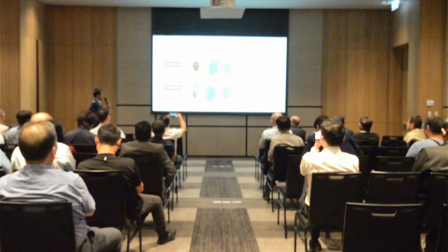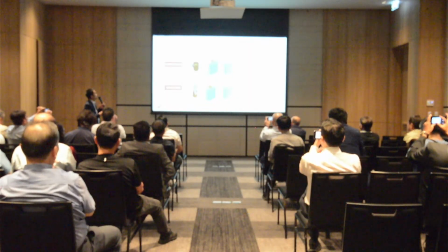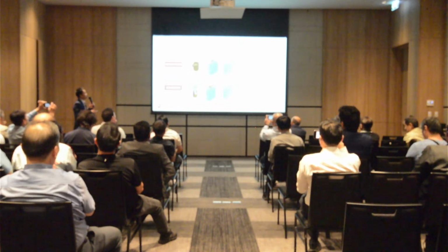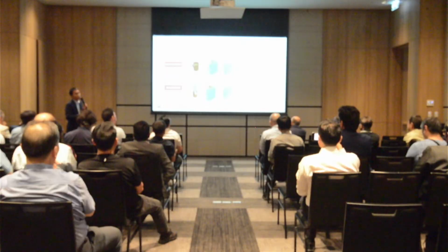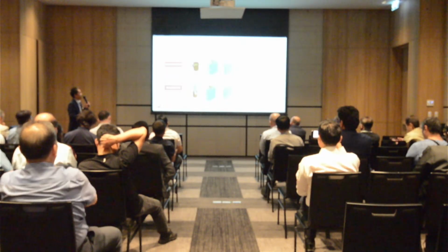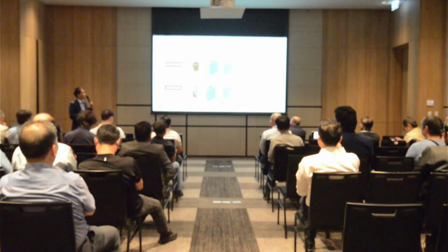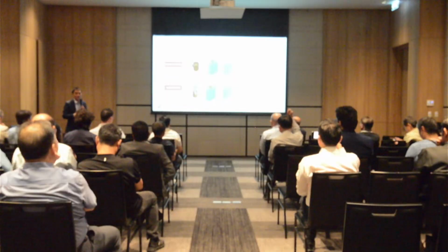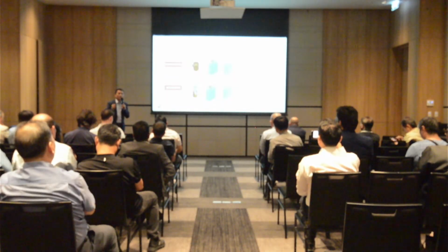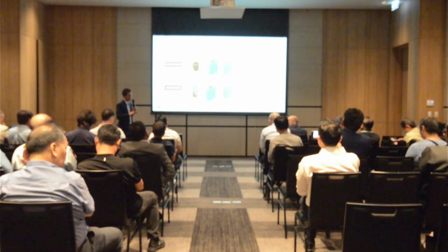we do this test, and we know for gravity casting, normally we use 356 alloy. The casting temperature is normally higher, and then you need a big riser for feeding. But for slurry, our casting temperature starts at about 630, and we can reduce a lot of die time, and also shrinkage, to increase the material yield. This is a target for the gravity casting: reduce riser, increase material yield, reduce die time for fast cycle.